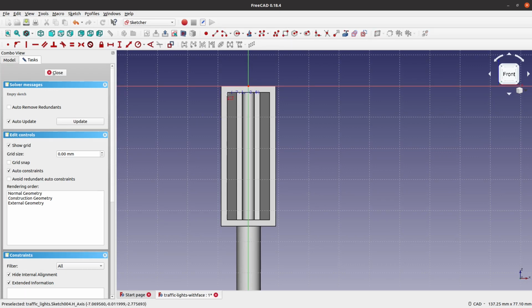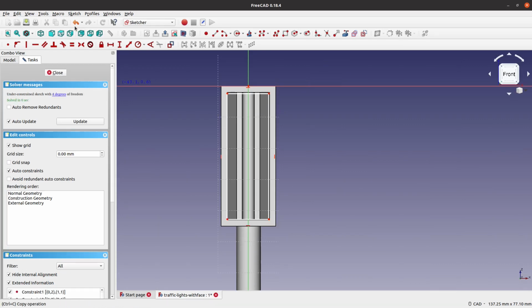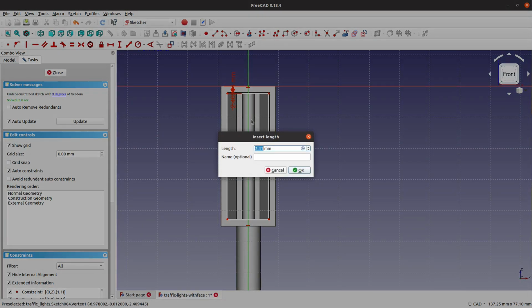Can create a rectangle which will be padding out, which will go inside the traffic light. It'll be roughly there. And we can use this plane, the points, as a reference point for the constraints. So if I do the height first here, this would be 2 millimeters, which would be the distance of the outside of there. However, because of the way we're going to 3D print them and want them to be able to insert into each other, I'm going to take the entire dimension 0.5 millimeter smaller. So I'm going to put 2.25 there.